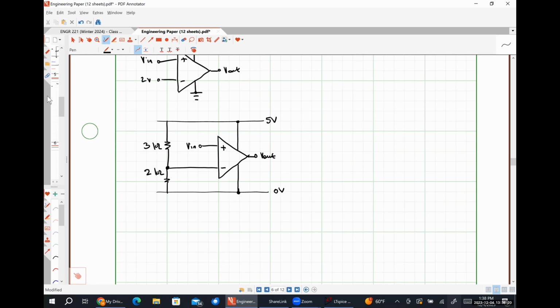That's part A. I say that because what's your peak value of your voltage here? 1.5 volts. What's 1.5 times 12? 18. Is 18 less than VCC plus? It is. So there's not going to be any saturation. What is negative 1.5 times 12? Negative 18. Is that more negative than negative 20 volts? It is not. No saturation distortion. So it's literally going to be this exact graph, except where it says 1.5, make it say 18.